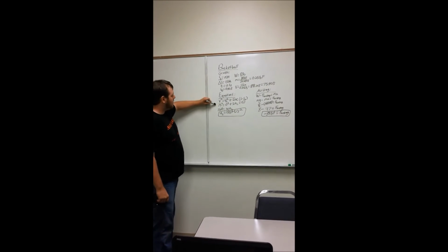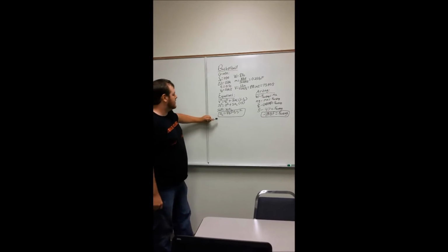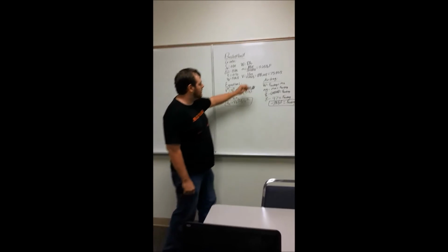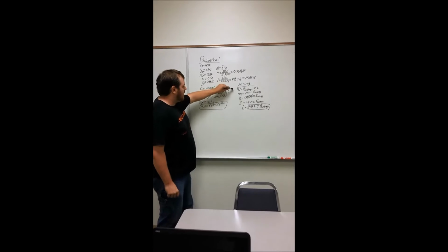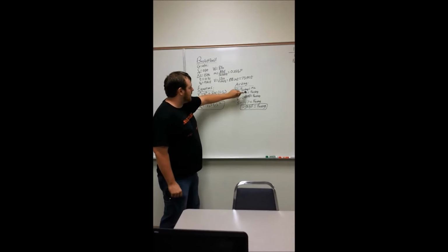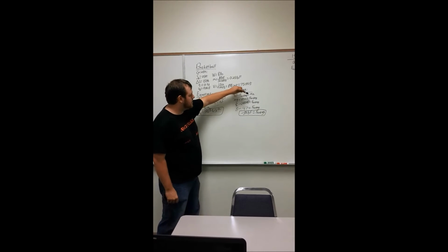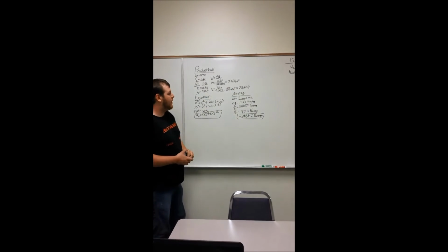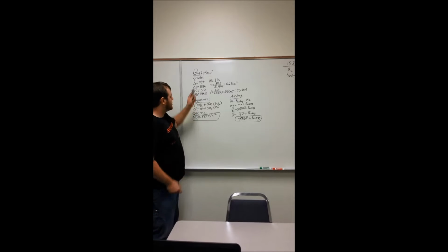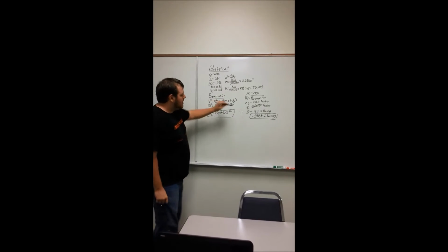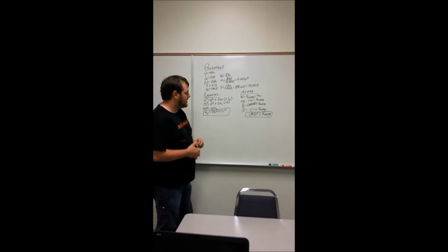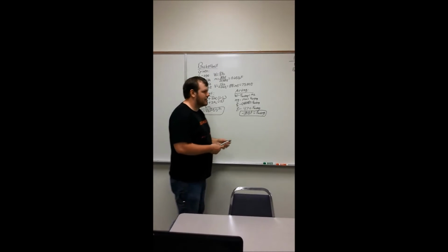Plugging in the given in the same manner, we were able to get that the constant acceleration is 118 feet per second squared. Again, air drag is the same thing: weight minus force of the air drag equals ma, which breaks into mass times gravity minus mass times acceleration equals force of the air drag, which, plugging in our given as we did at 9 feet, gives us a negative 391 pounds of force. It's a lot of air drag.